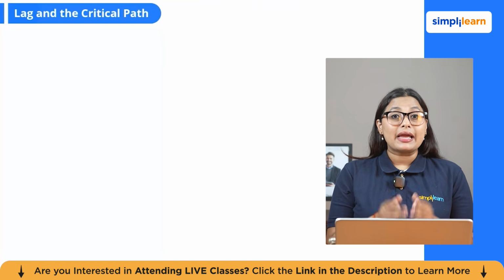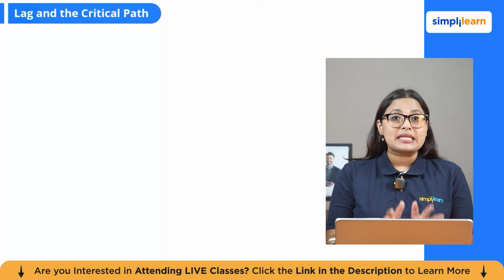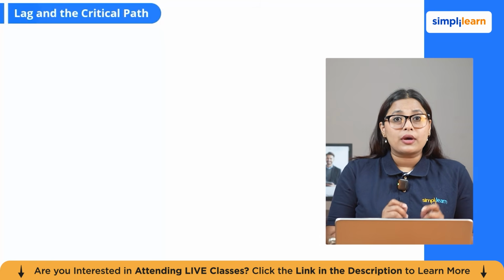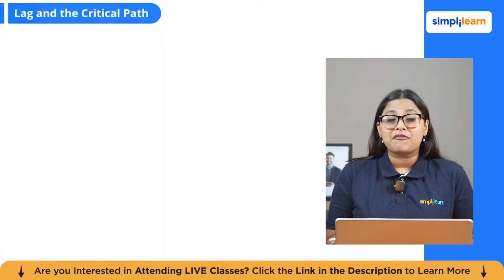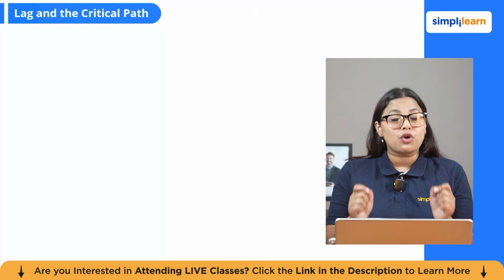You can also apply a lag to the relationship. For example, roofing might start 2 days after the frame finishes, to allow time for the handover inspection. You enter this type of lag in the relationship, and MS Project factors it into the date calculation automatically.